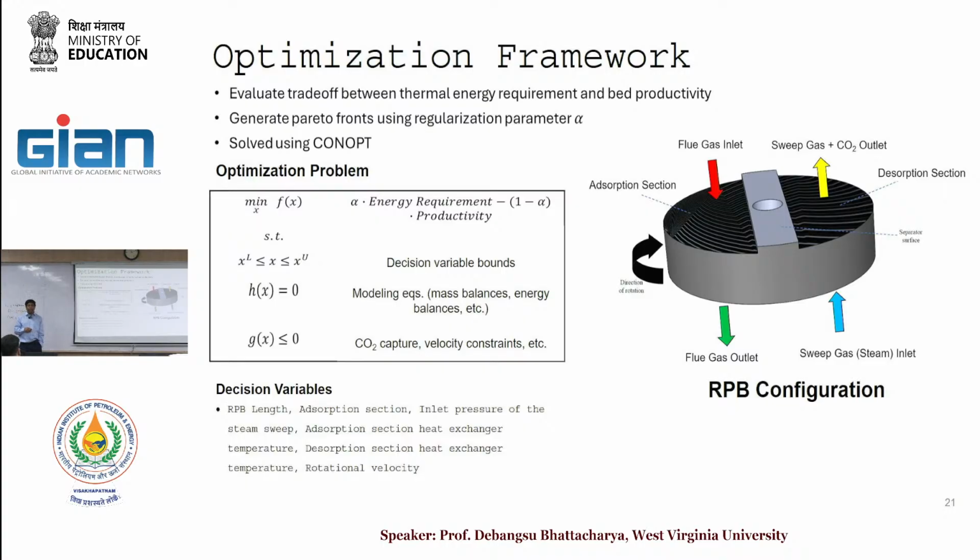But this flue gas that goes through here is coming in contact with the solid sorbent which is already loaded, right? So you really do not want a lot of flow coming through here, because if that goes there, then it is already in contact with the loaded sorbent, so there is not much opportunity for capture. So this is a distribution problem.